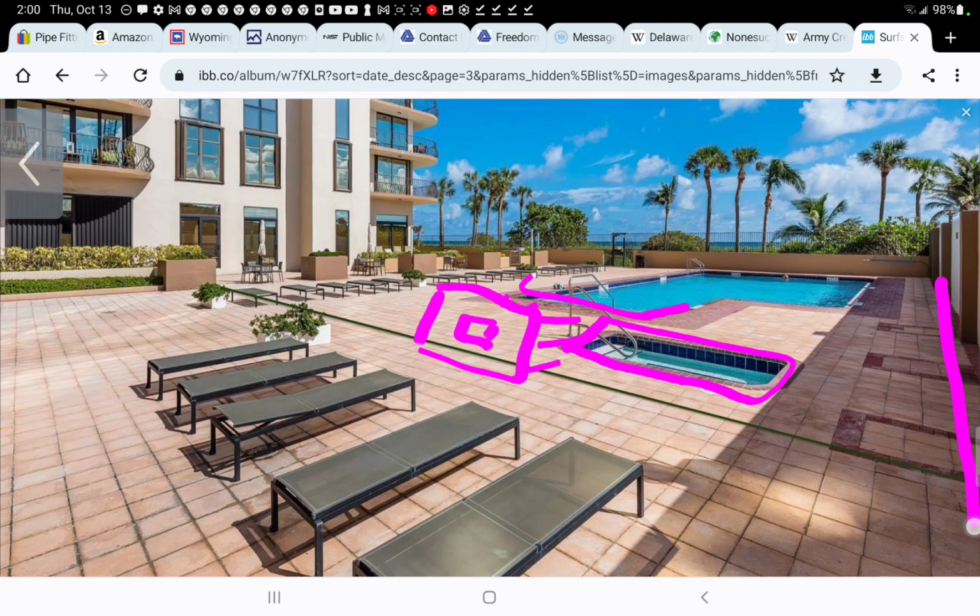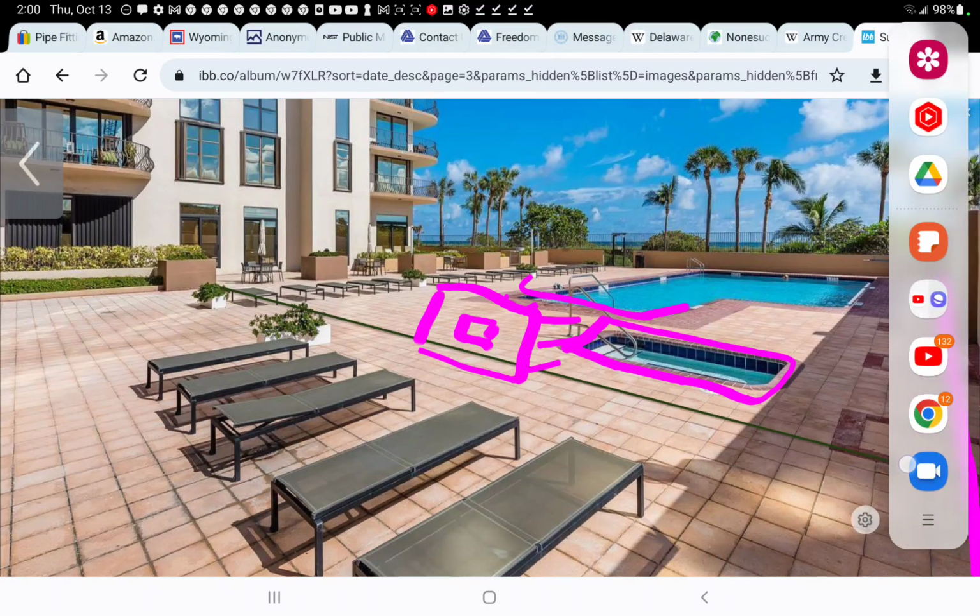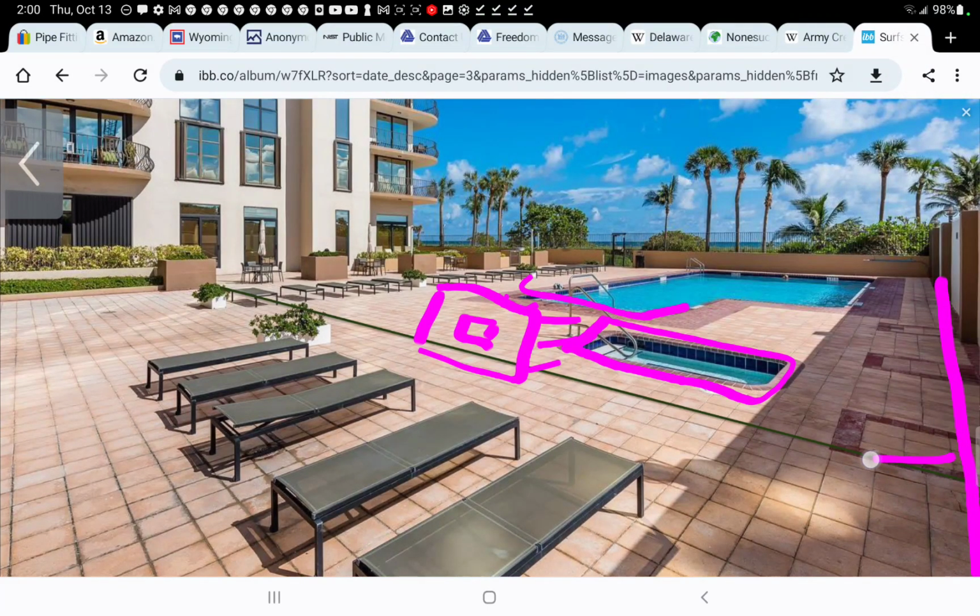Our back wall, same thing. So the back wall is there. And now we have that, I told you it's going to be a little bit of a cantilever effect, where it's going to be more rigid. And then this will become the tributary zone between, well, let's do two tributary zones. The lower deck has its own tributary zone, let's look green, right up to the column. All right, correction, right over the column even.